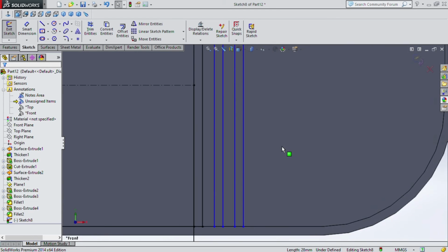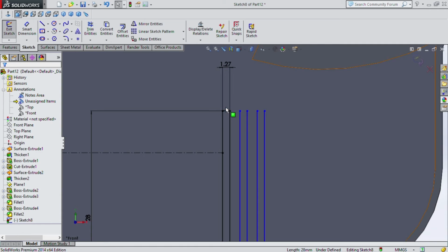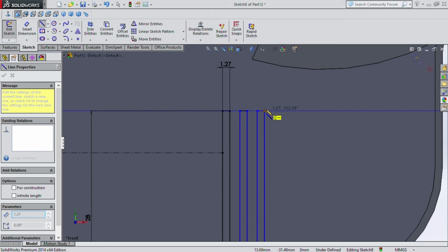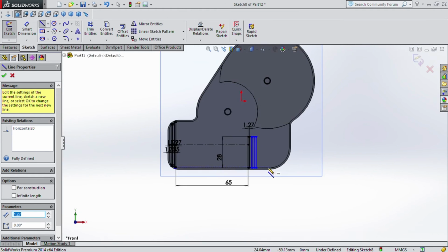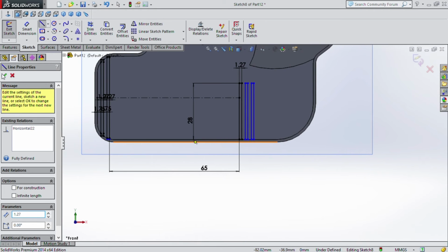So essentially we just wanted to leave a space of 1,75 there, make our geometry with the width of 1,27, just like here. Then leave another space of 1,75, make a geometry with a width of 1,27 again. Then now we select line, want to cross there, there, and there, then select there and there again, there and there again, and we're done.